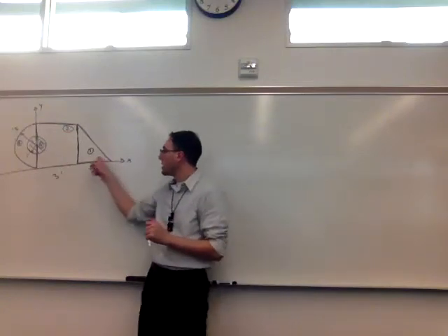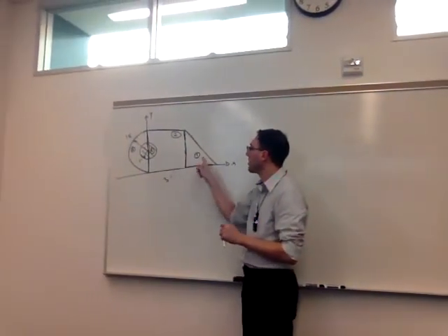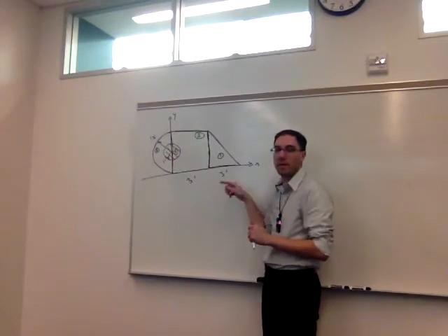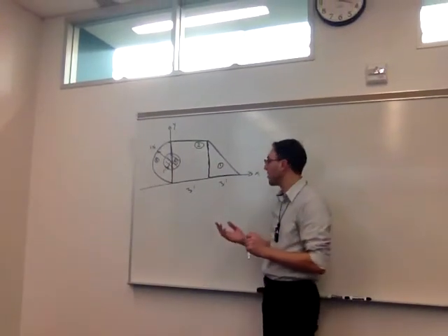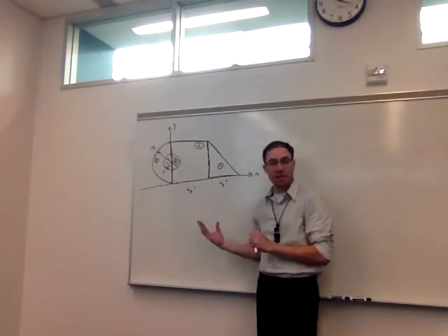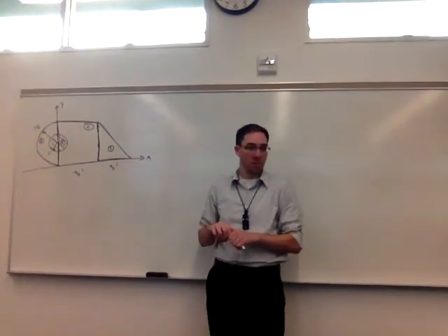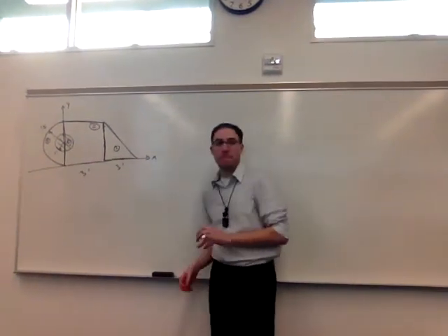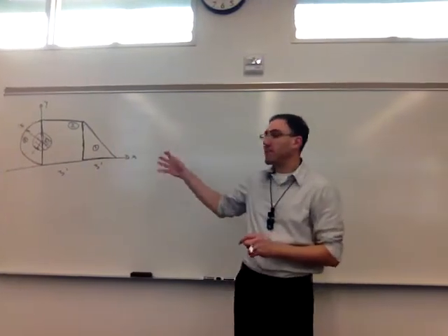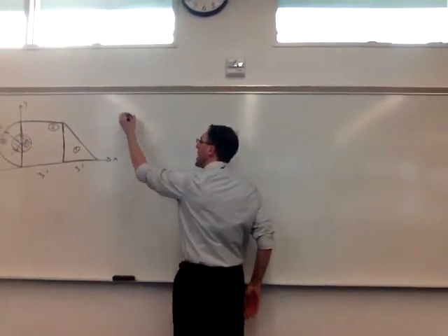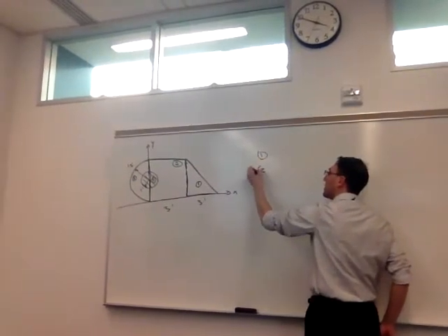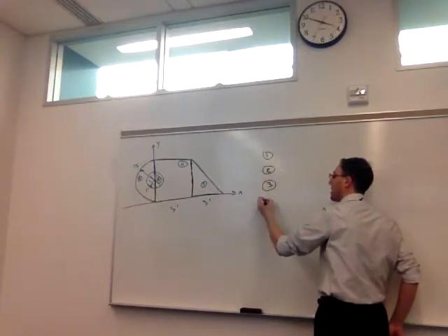All right, now, one and two, you could have kept together as a trapezoid. I would say just use simpler shapes even than trapezoids, so rectangles, triangles, in this case a half circle, a full circle, sometimes we'll see quarter circles. All right, so we have established the shapes, so now we can start our table. So we have four shapes.